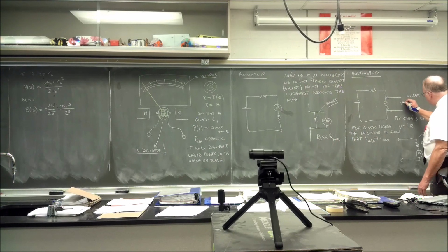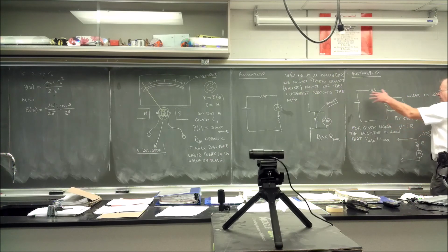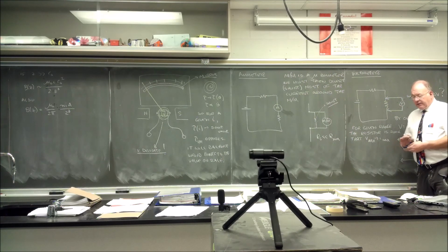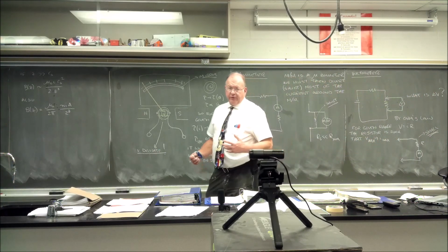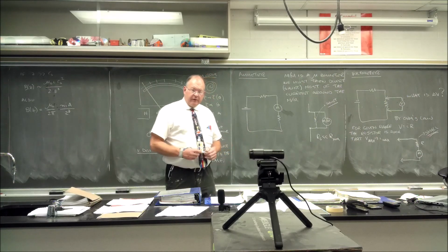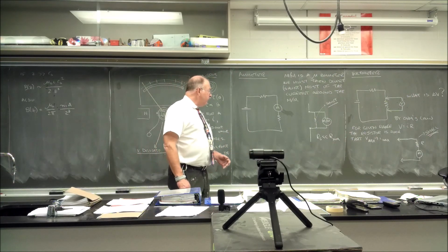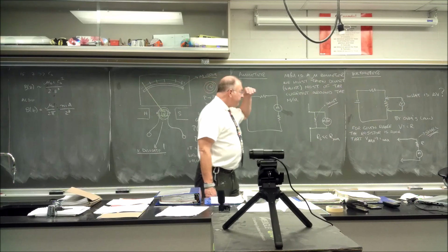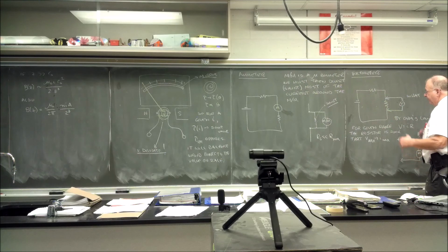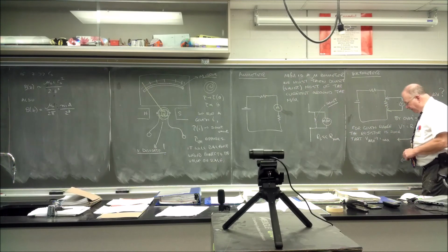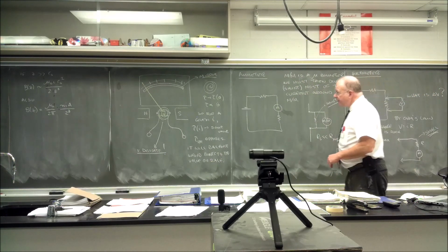So when we have our circuit here, the current is flowing through here like this. If this is a kilo ohm resistor or whatever, and this thing is 50 mega ohms, the amount of current flowing through here is irrelevant, and it's not going to materially affect the performance of the circuit. So the objective, of course, is that the act of measuring does not materially change the circuit, and that you can do it fairly efficiently. Ammeters are the biggest pain, so oftentimes we use the voltmeter and just tap a circuit, boom, boom, boom, and see what's going on. And that's often done.